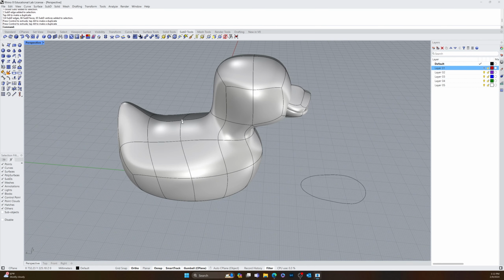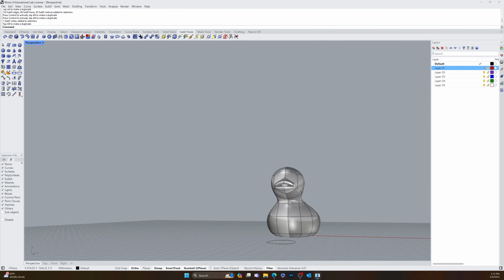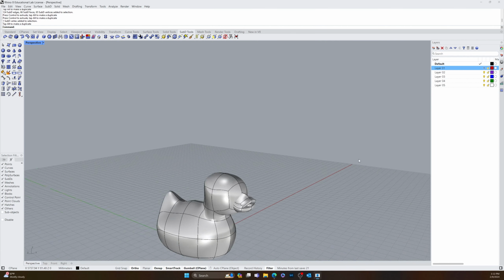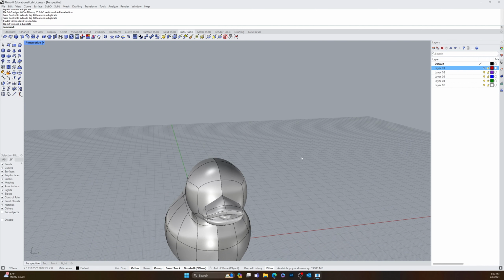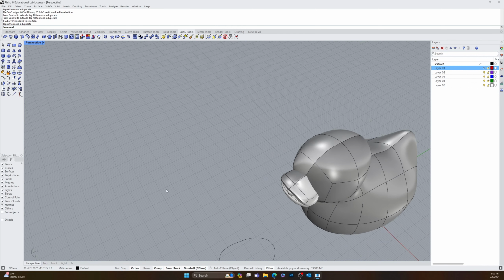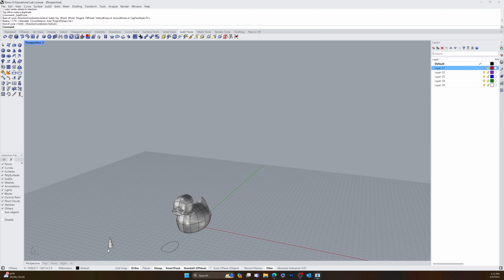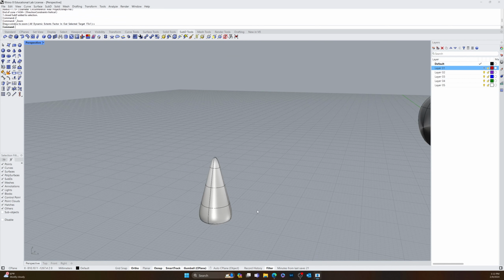And then grab this spot here, kind of move it up, arch the duck back. All right, cool. Next thing I want to do is add a little tuft of weird hair on the top here. So I'm going to do that by doing a few sub D cones. So just like this: Z, enter, S, enter. And so with a sub D cone,